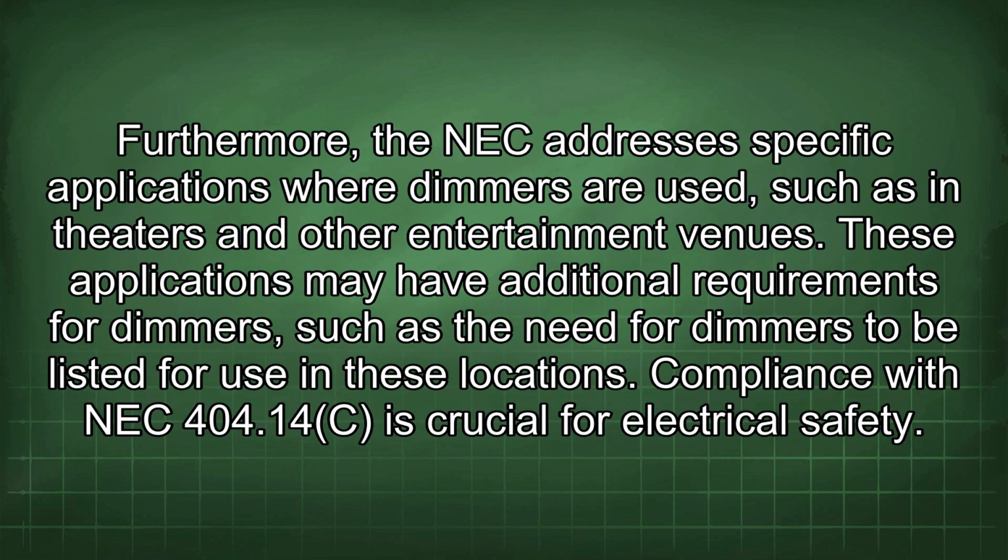Furthermore, the NEC addresses specific applications where dimmers are used, such as in theaters and other entertainment venues. These applications may have additional requirements for dimmers, such as the need for dimmers to be listed for use in these locations. Compliance with NEC 404.14c is crucial for electrical safety.